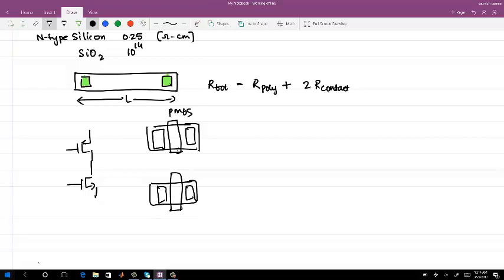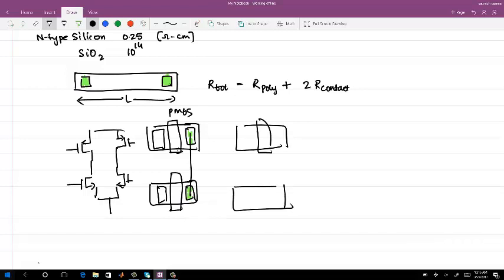Let's say I connect these two drains. In order to connect these two drains through metal, I will have contacts on both sides. And if I'm using this circuit as a differential circuit, similarly I will have another differential block, with the same source and drain, and I connect that through metal.